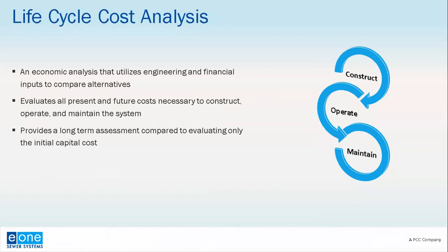One of the things that we also look at as part of this ongoing dialogue with end users and stakeholders about when to utilize pressure sewer is life cycle cost analysis. This is something that, to my knowledge, we're the only organization out there that does this, in comparing different types of collection methods and costs related to those methods. But what it is, is an economic analysis that utilizes engineering and financial inputs to compare alternatives.